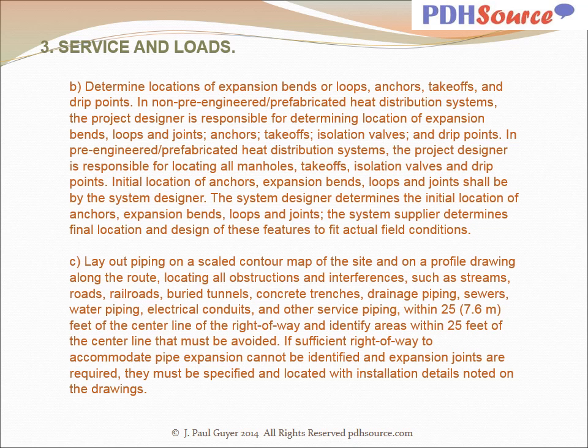In non-pre-engineered, prefabricated heat distribution systems, the project designer is responsible for determining location of expansion bends, loops and joints, anchors, takeoffs, isolation valves, and drip points. In pre-engineered, prefabricated heat distribution systems, the project designer is responsible for locating all manholes, takeoffs, isolation valves, and drip points. Initial location of anchors, expansion bends, loops, and joints shall be by the system designer. The system supplier determines final location and design of these features to fit actual field conditions.